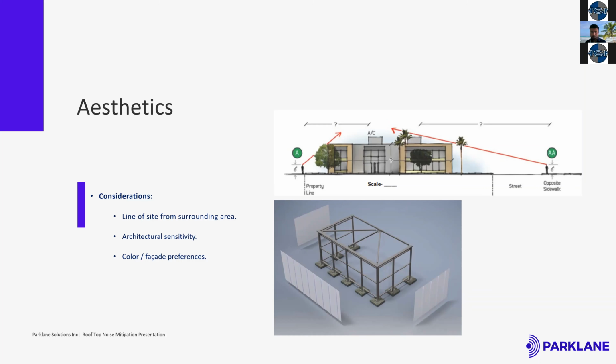That's the idea. And in this instance, how you would go about mitigating it, again, the noise is coming from the air handling unit. So you just stick a silencer in it, make sure that the pressure losses do not impact the performance of the air handling unit itself, and make sure that the NC rating is met at whatever room the air is being serviced to. So that's what an NC rating is.